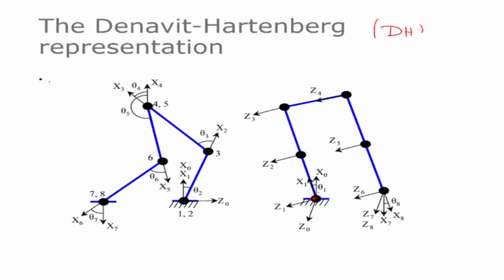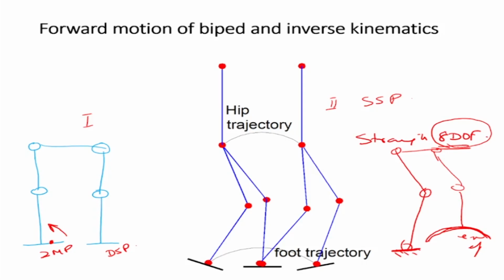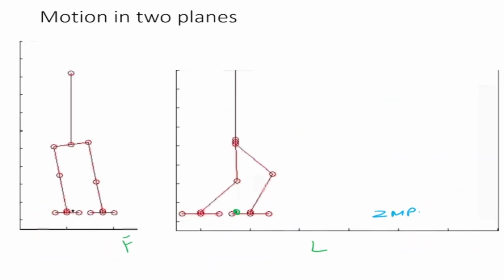So first joint, second joint. At the hip, let us go back a little bit again here. If it is bending on one side, it needs 1 degree of freedom. On this figure, it is bending this side, so it needs 1 degree of freedom there. Then this is behaving like a 2-link manipulator, so it needs a 2nd degree of freedom at the ankle. 2, 3, and 4. So each leg has 4 degrees of freedom.